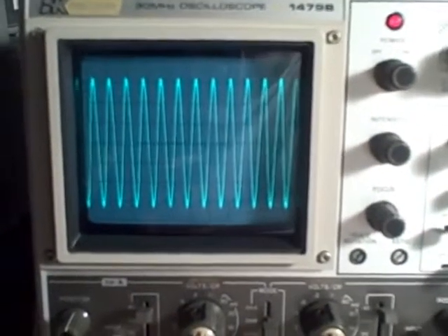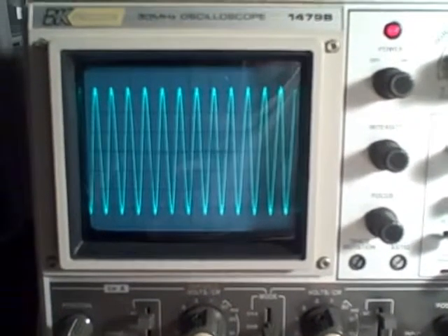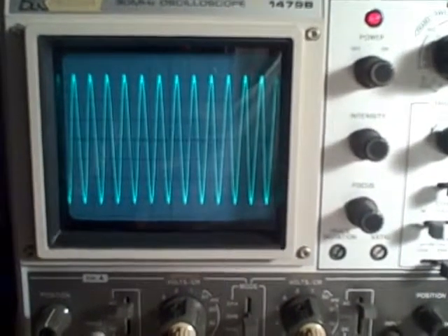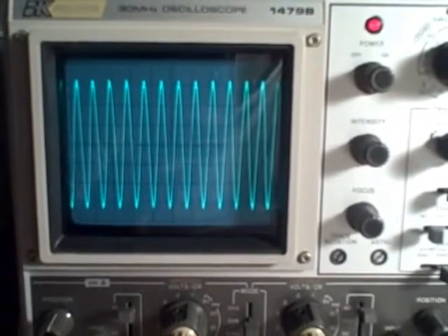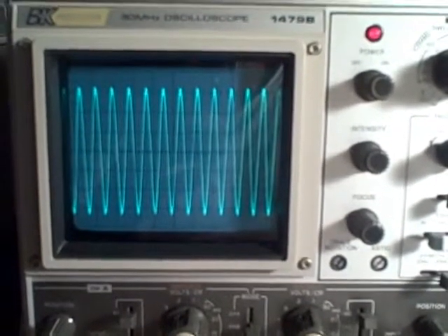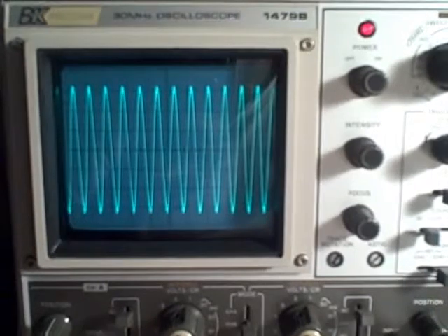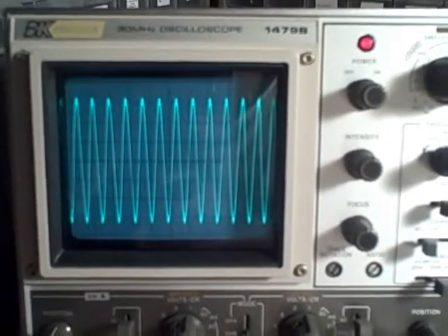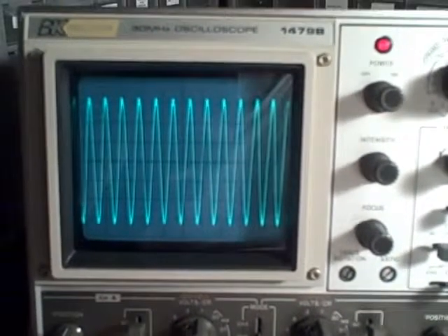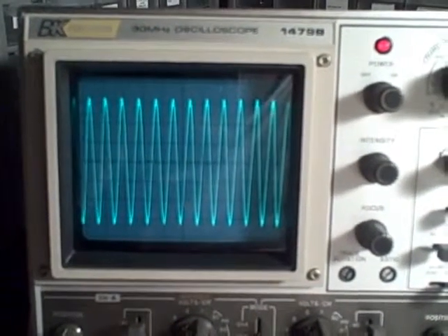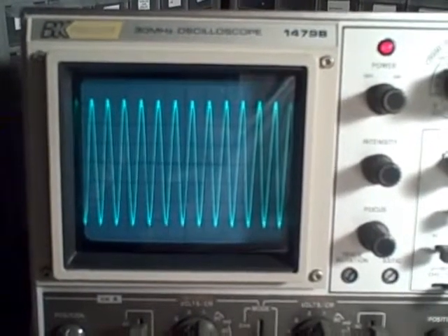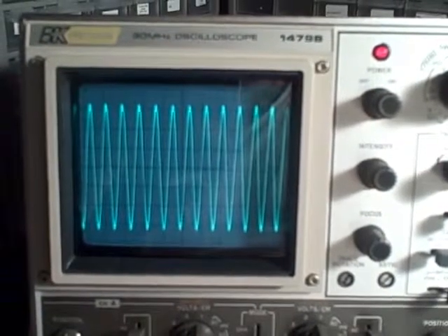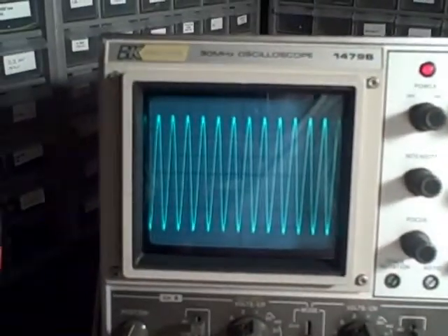And what we see is that at the same 10 millivolt per division scale, we actually are a little more improved on our bandwidth on channel B. So we are down 0.8 and up 0.8. So instead of being 1.2 plus and minus, we are 0.8 off. A little bit better bandwidth.